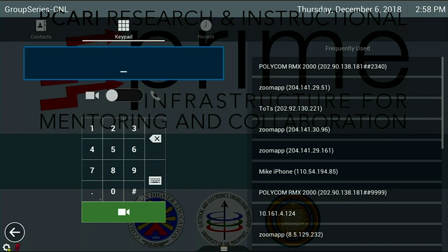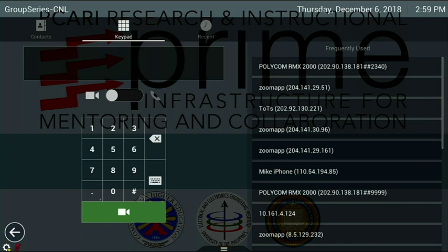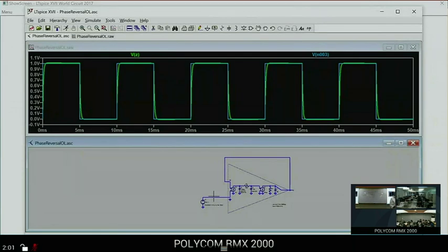If you want to make something an oscillator with feedback, look at it in the time domain. If you put a signal in the amplifier, and the output of the amplifier looks exactly like what you put into it, well, if you take the input and output and connect them together, it could just run forever. That's an easy to understand time domain picture of stability, and that picture is correct. And you can apply it here to understand why this is stable.